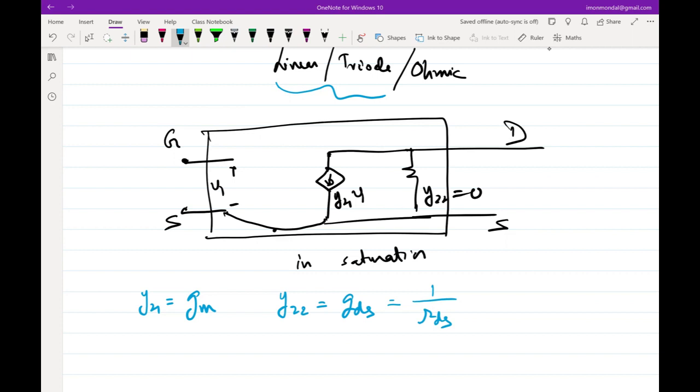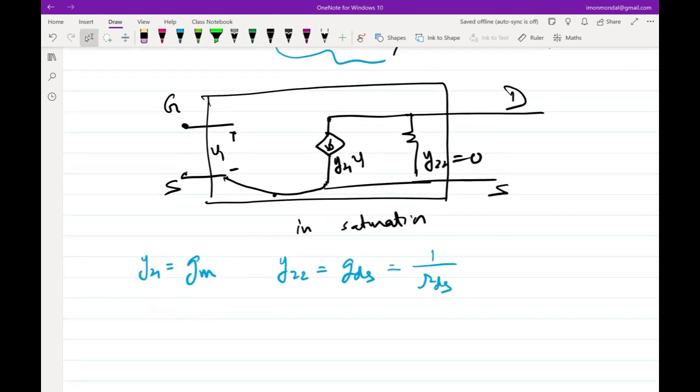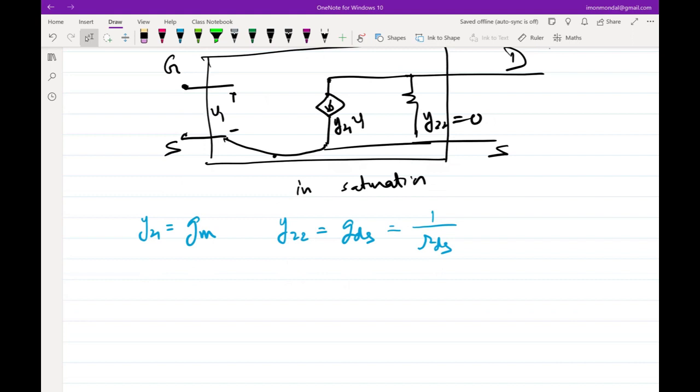Okay. So now that we have arrived at a situation where we can use this MOSFET under certain conditions, not always. It's not as if you take the MOSFET and plug it in and apply an input and output, you are going to get an amplifier. You have to first massage the MOSFET and make sure that the MOSFET gets into the saturation region, and then apply an input, and then you can hope that you can get some sort of amplifier out of this contraption.